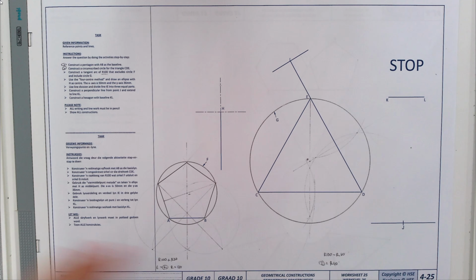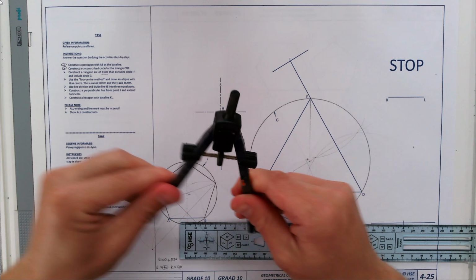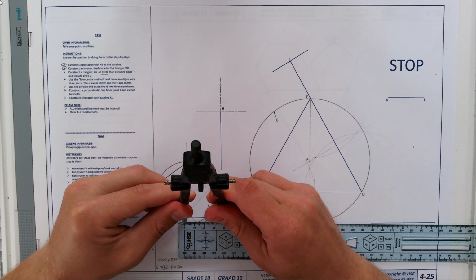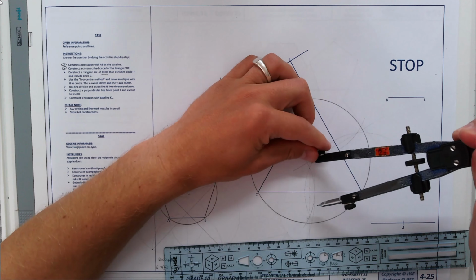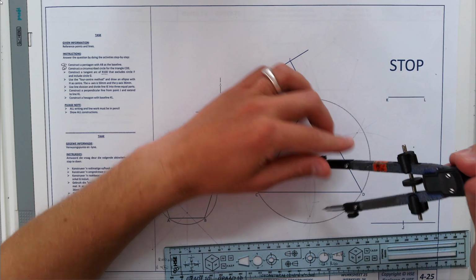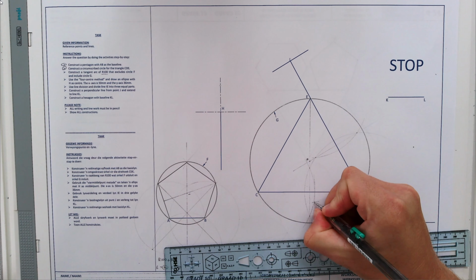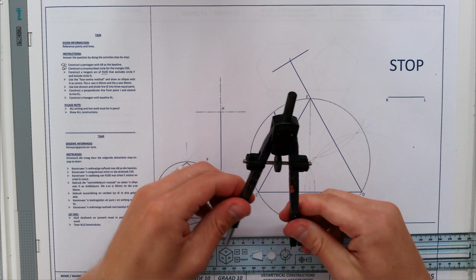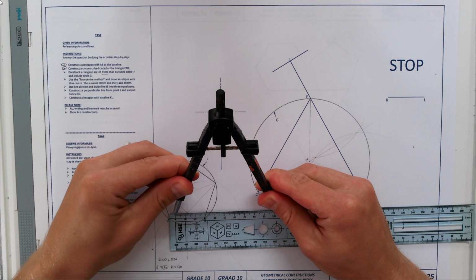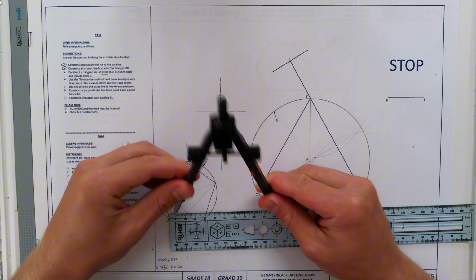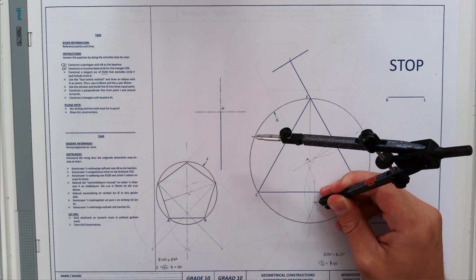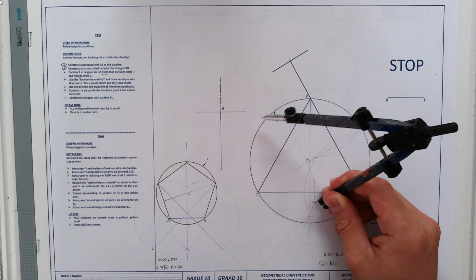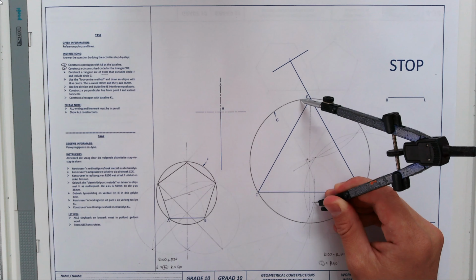Then we're going to set it on the 40 for circle G. That is what we calculated. 40. Sharp point at M in the middle, and there where they connect, that is your point where you'll put your sharp point for the tangent arc of a radius 100. So now I'm going to set my compass to the 100. You put your point there, and then this arc should go from that circle all the way to this circle as a tangent arc.